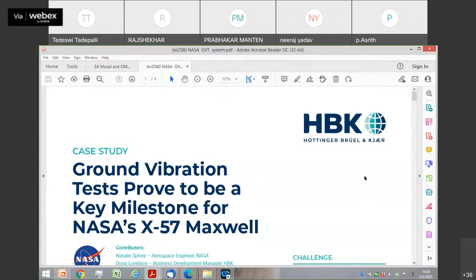Actually, I want to measure a shock on a gun barrel, approximately 20,000 G. Is there any miniature sensor so that I can mount there? Yeah, we have done similar measurements just a couple of months back in Pune on gunshot measurements. In these sort of techniques, you could have shock sensors which are 100,000 G mounted. And then what is important in such cases is you would use a technique called SRS, shock response synthesis, wherein it tells you what is the shock at that point on the gun barrel.